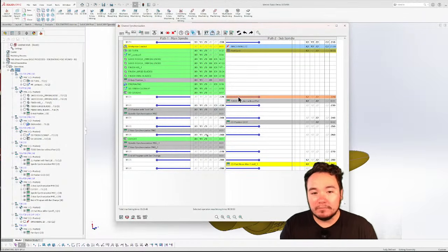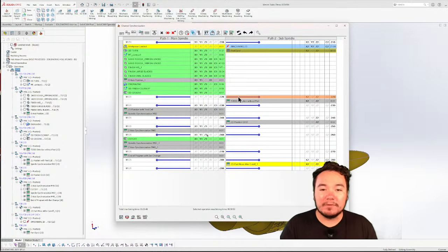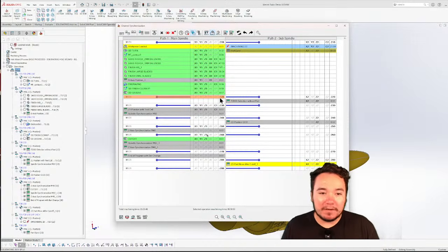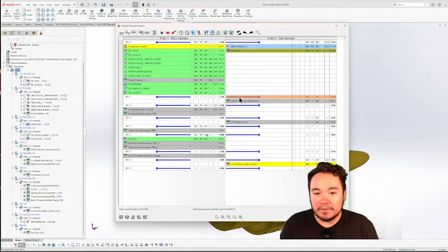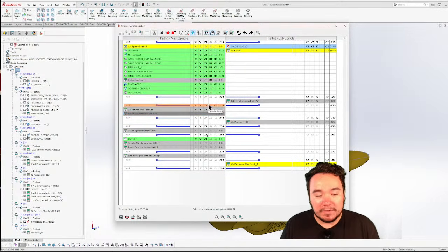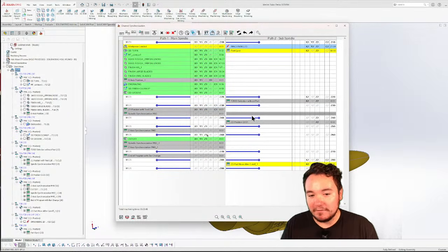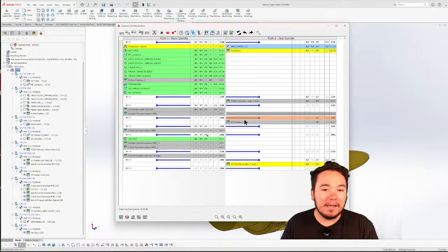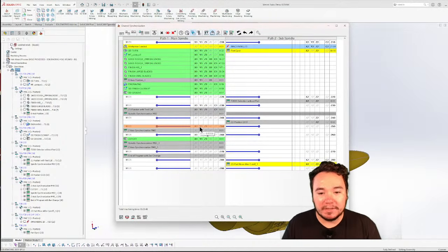Right after it's done with the iMachining, it'll part eject, and then the sub won't keep going until the end of the wait code hits on the main. So you'll see a wait code there on main and sub to synchronize them, and then once it hits those, it'll go T2000, but it'll wait. Obviously we don't have anything in the main, and then we'll have the next two happening at the same time on the main while the sub is waiting for the main to go through it, and vice versa as we go down the tree here.